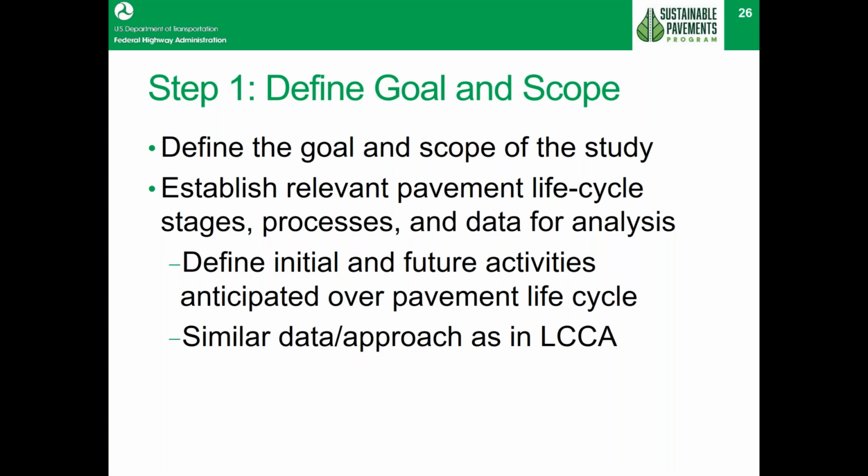As an example, an agency may have the following LCA goal: to determine the environmental impacts of a pavement structural design. With that goal established, the scope needs to be defined, with a partial list of some of the items to consider in developing the scope listed. Which life cycle phases are we going to include in this study? Is it going to be a cradle to gate study, or will this be a cradle to grave study? Are there some pavement life cycle stages that will be excluded?